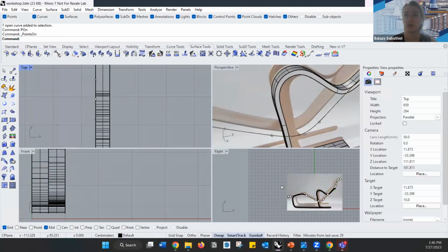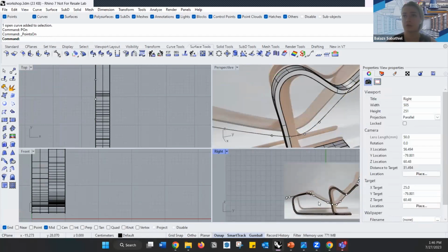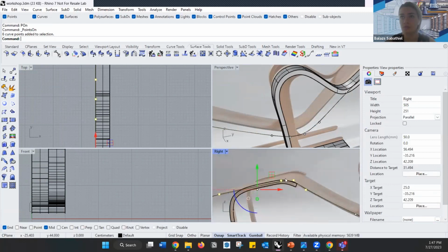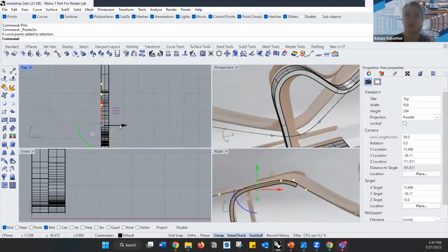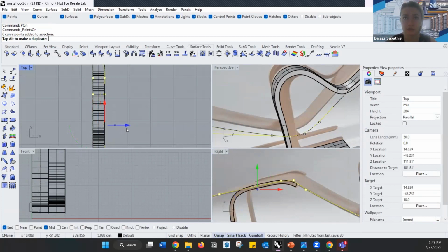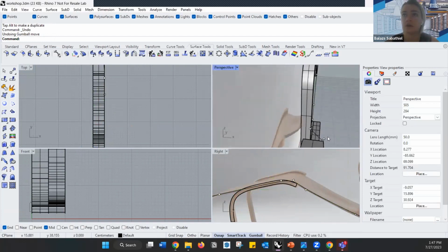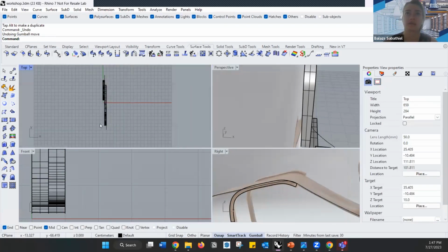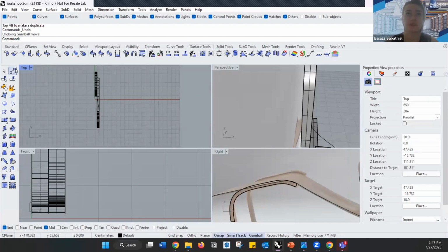Points on. And I can do it in any view, but I'm going to select them from this view. I want to move all of these points to the right side of this leg. So I will do that. I could have also done it with the precision, so with the distance. And now you can see that the curve does this little kink, let's say.